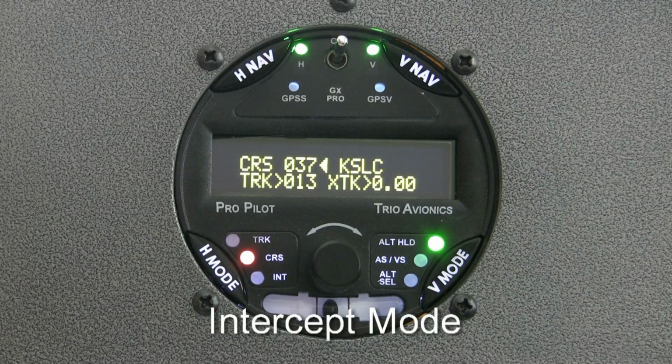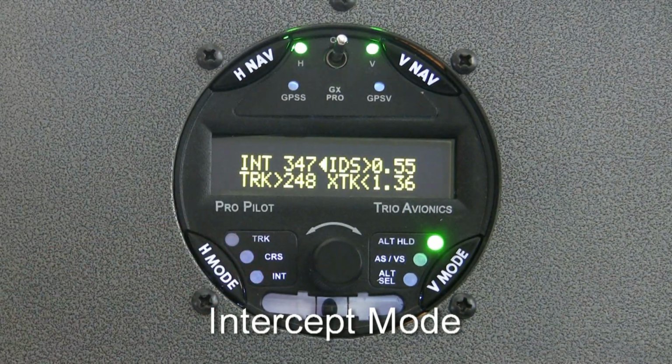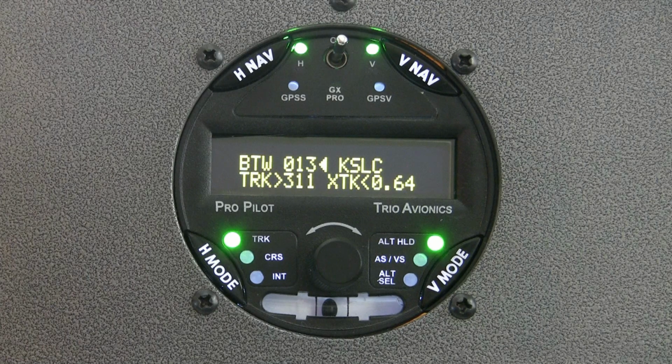The pilot can return the aircraft to the original flight plan by simply pressing the H-mode button to enter the intercept mode. The aircraft will then turn to intercept the original flight path at a 30-degree angle. This intercept angle can be adjusted by rotating the encoder knob. Once the aircraft nears the original flight path, it will automatically return to the track mode and resume normal navigation.